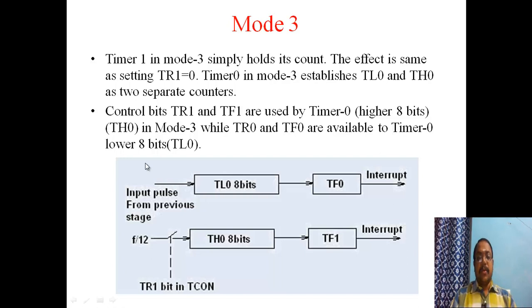Then comes mode 3. Mode 3 is a small thing you have to understand here. Both your flags, that is the overflow flag of timer 0 and the overflow flag of timer 1, are handled with the help of only the 8-bit content of timer 0. Timer 1 is not being used here, only timer 0 is being used, whereas the flags of both timer 0 and timer 1 are being used.